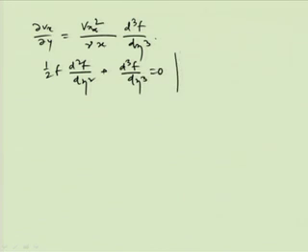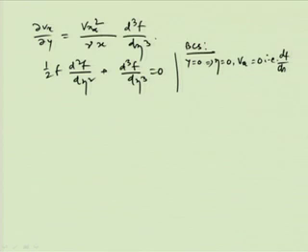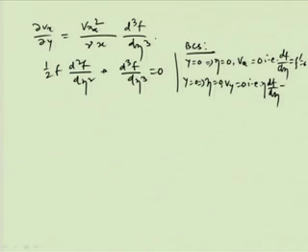And the boundary conditions are: y equals 0, that means eta equals 0, Vx equals 0, that is df by d eta equals f dash equal to 0. Another condition is y equals 0 implies eta equals 0, then phi y equals 0, that is eta into df by d eta minus f equal to 0, which implies f equals 0.